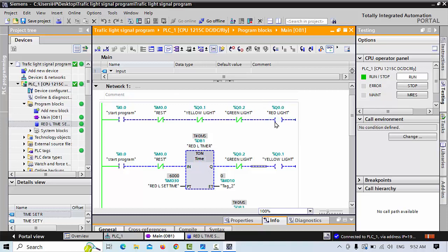For motors also, in this program you can change the tag names and everything, and you can use this for washing machines, or where motors run in reverse and forward conditions. For example, you can give this Q0.0 for the forward condition, and this coil for the reverse condition.